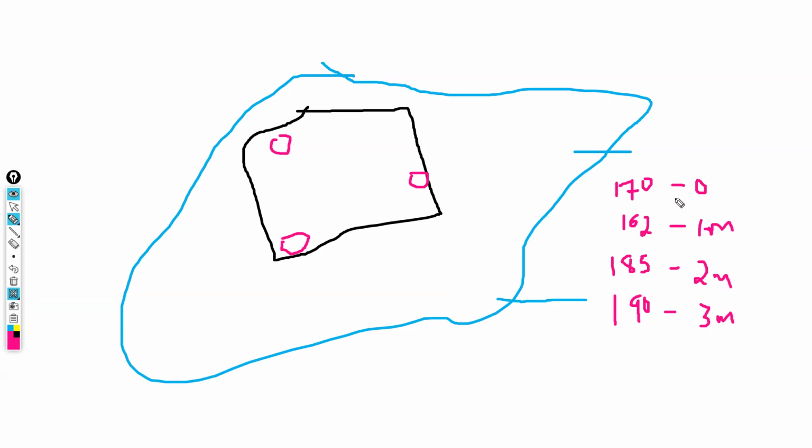So the bearing capacity or the foundation design is going to be based on trial pit 1 because it is the one having the least bearing capacity. Then that bearing capacity was obtained at a depth of 1 meter. So therefore, that distance of 1 meter is what you're going to have in that input. Is that okay? Yeah.